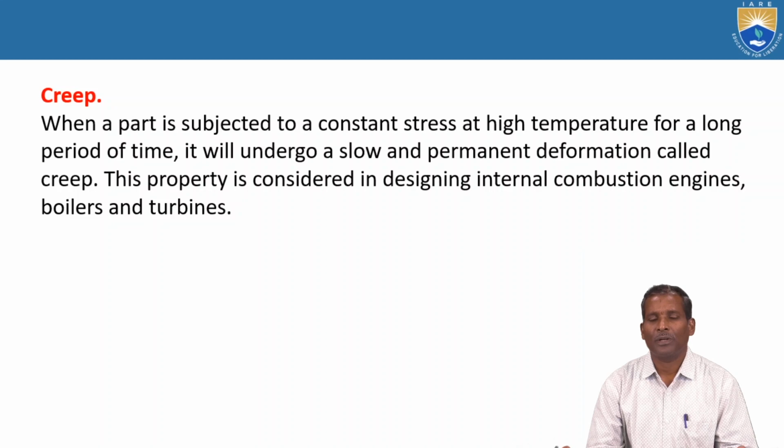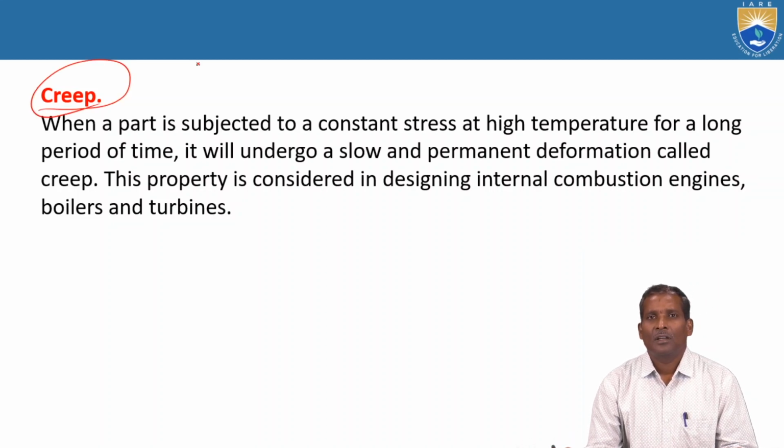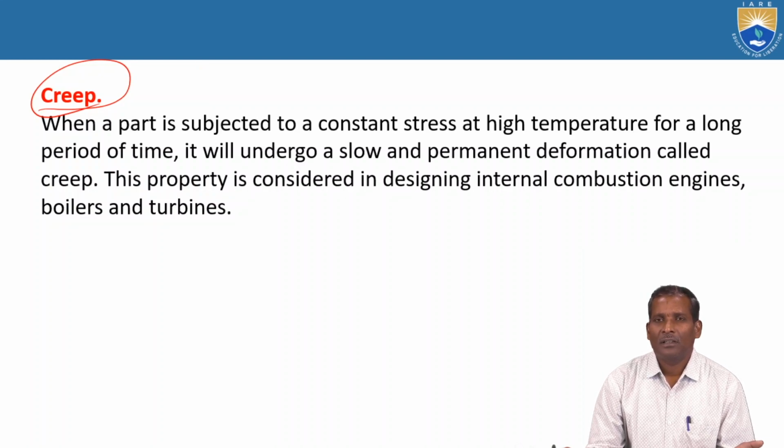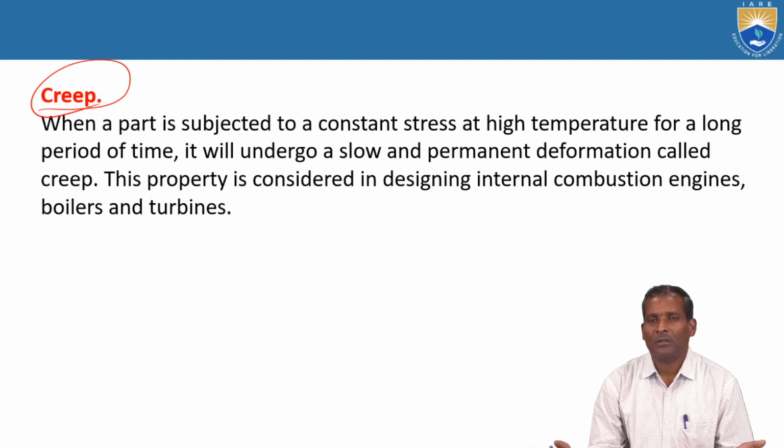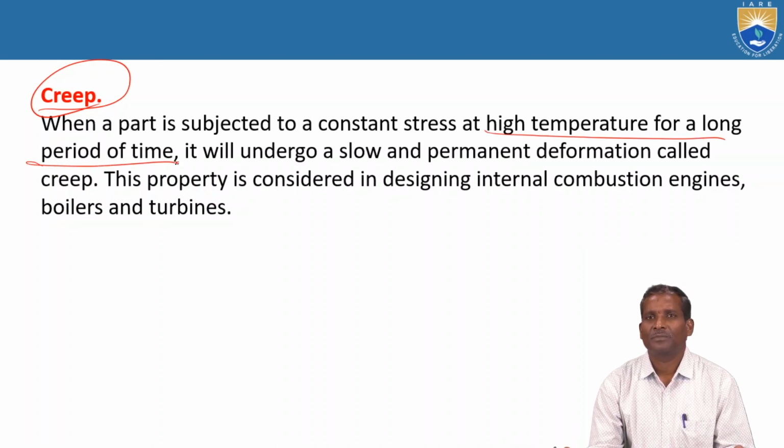Next one is the creep property. When a component, element or part is subjected to a constant stress, not a variable one, at high temperatures for a long period of time, it will undergo a slow and permanent deformation called creep.